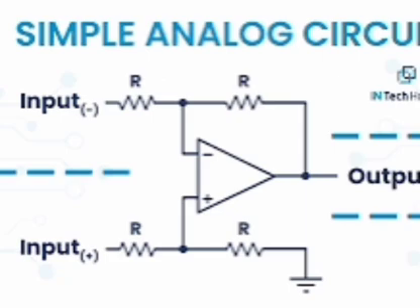Critical inductance LC is the value of inductance used in LC filter at which peak AC current in the circuit is equal to DC current. LC equals RL by 3 omega naught. For half wave rectifier, R equals pi into modulus of XC in the numerator, 2 root 2 XL in the denominator. LC equals pi RL by 2 omega naught, where XC and XL are calculated at omega equal to omega naught. Capacitor filter,